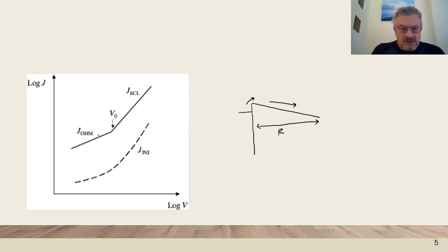This can be ohmic transport. At higher bias, it can go into space charge limited current, for example. When the initial carrier density is exhausted, you need to sustain more charge to increase the current. But there is also, besides this transport resistance, an interfacial charge transfer resistance at the contact.